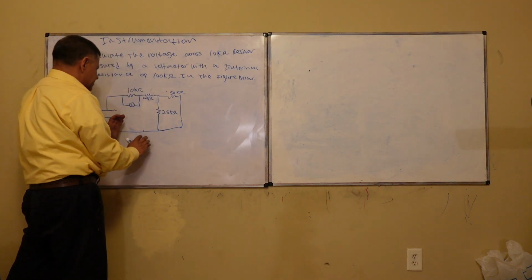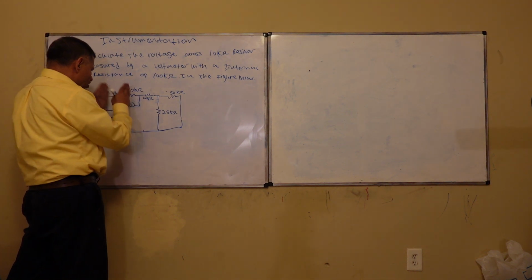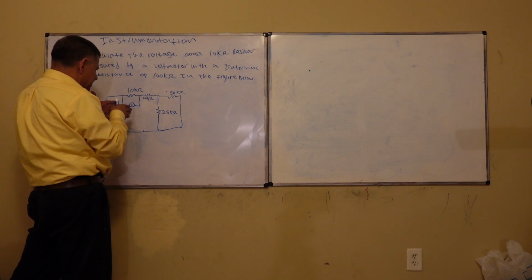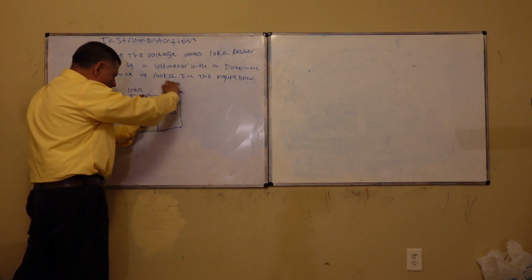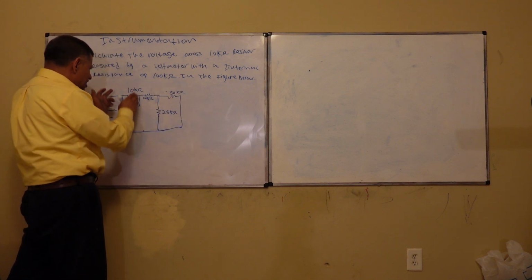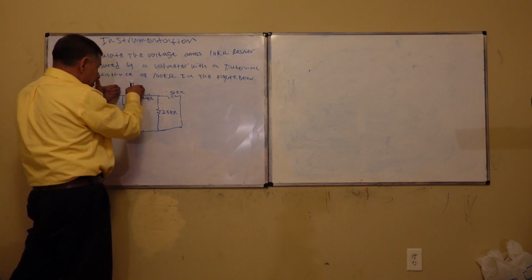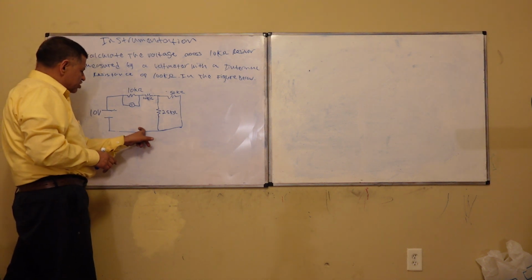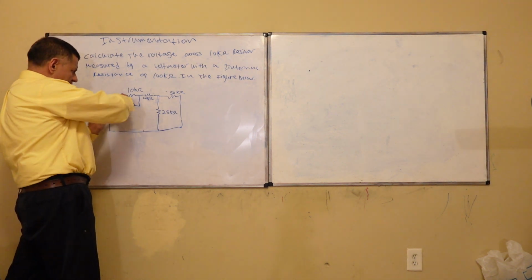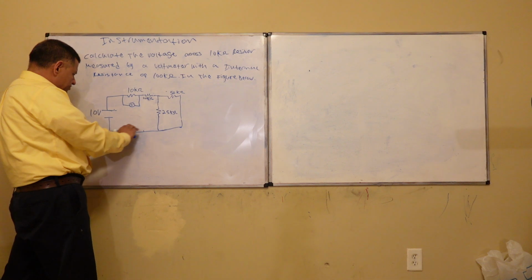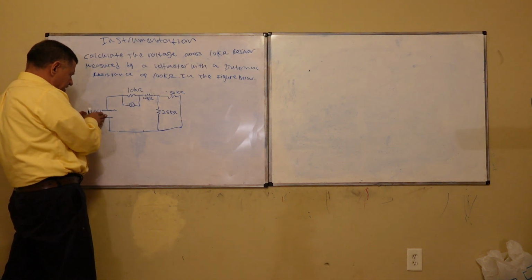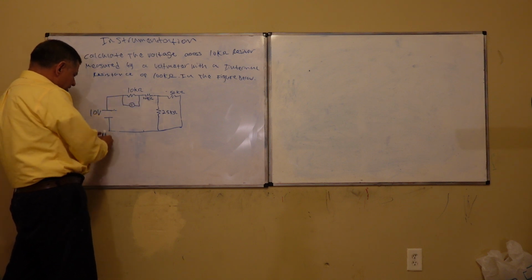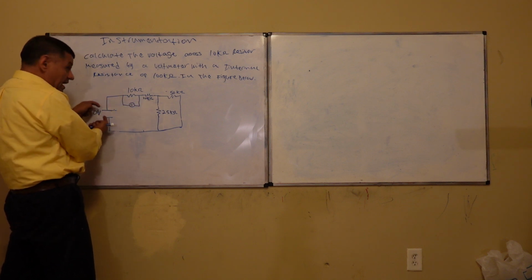So now we calculate this resistance because we want to know the voltage across this, right? Why? Because we need to know the impedance in order to see what the voltage drop is in that one. Because the sum of the voltages going around the loop has to be equal to whatever voltage is coming from the source.